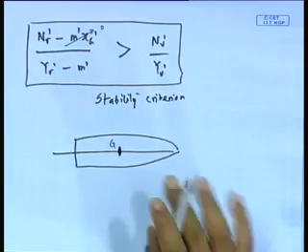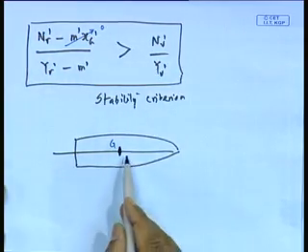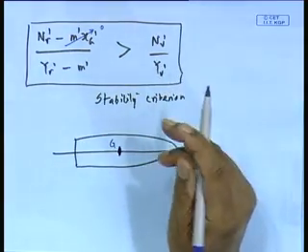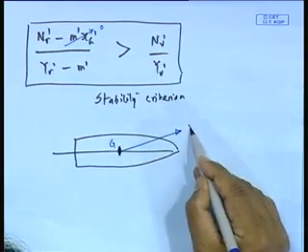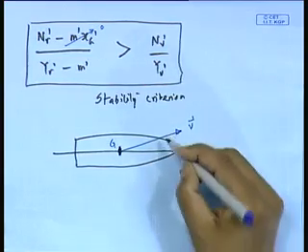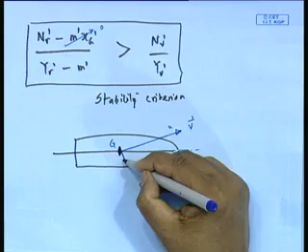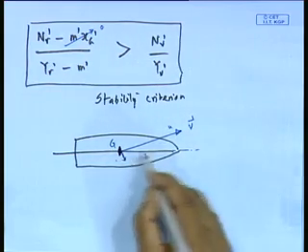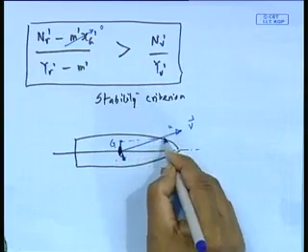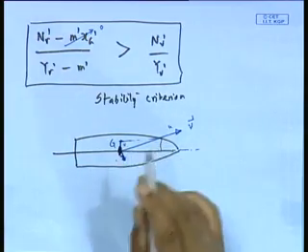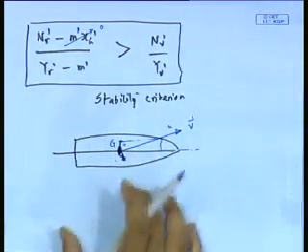You see what is happening. Now, understand this is very interesting. I have a ship moving. What is Yv? Y force because of v. What is v dash? V dash is angle of attack. That means I am going along this direction. So, I have got u here, I have got v here, this is my v, right. When I go at an angle of attack, I have a v here.